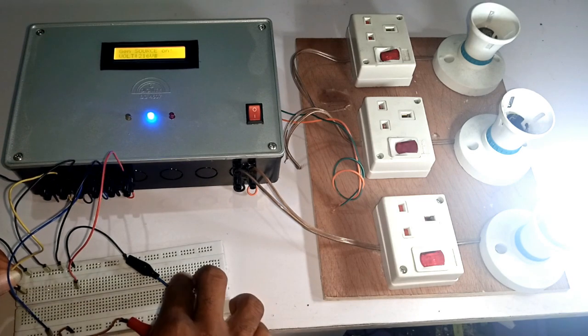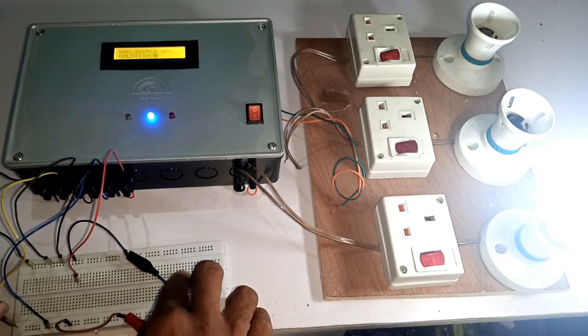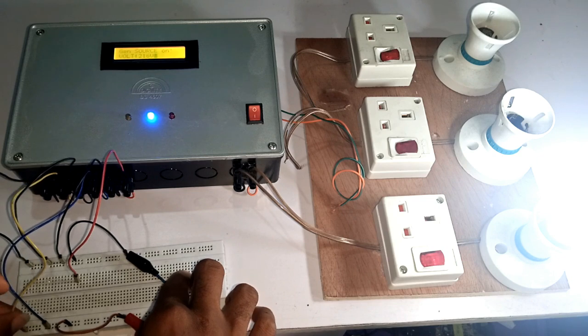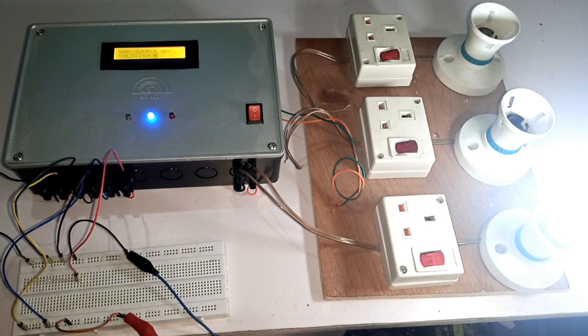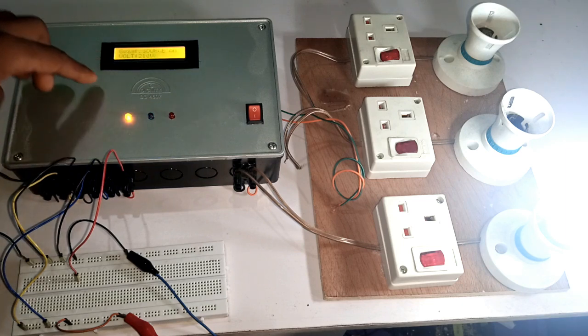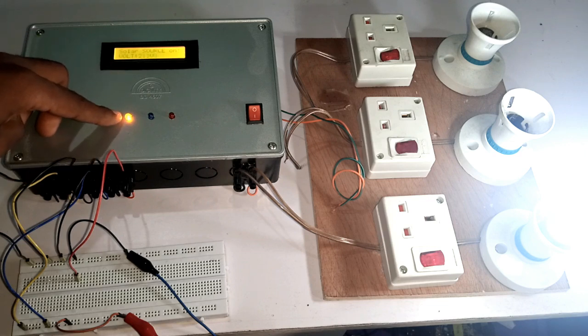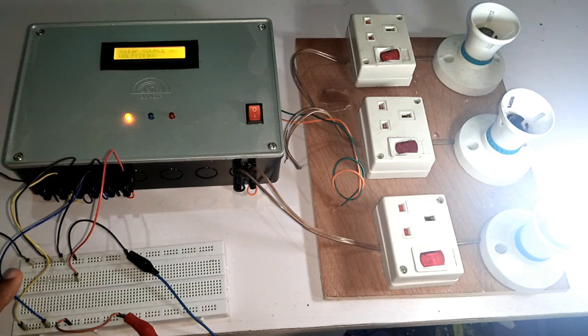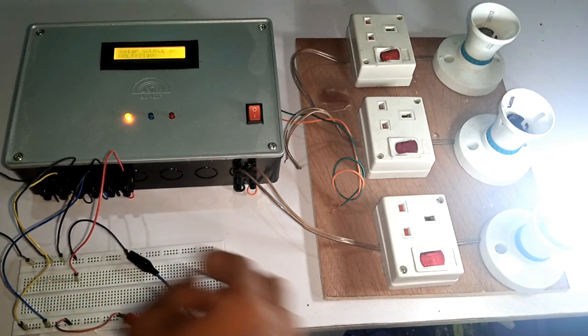Next, I hooked up the solar line, which is the yellow wire, to the AC source, and from the program line of code, the buzzer alarm will trigger for 10 seconds before switching the line. Just as you can see, the load shifted from the generator relay line to the solar relay line, and this happened instantly without having the bulb turn off.